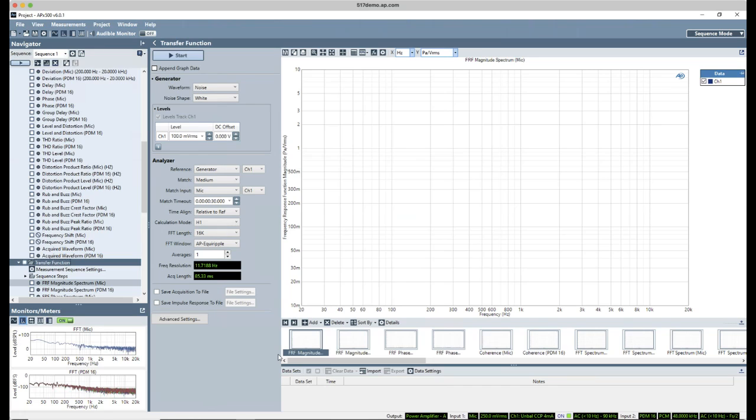And the application here is that we can make a measurement, we can find the frequency response and phase response, and therefore the sensitivity of a microphone, but using any signal we want. In this case, the greatest advantage is that we can use a non-sine wave based signal.